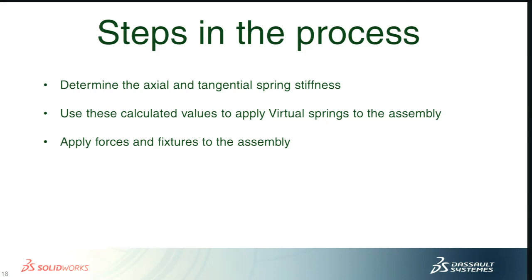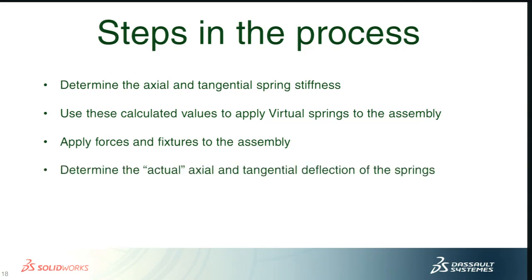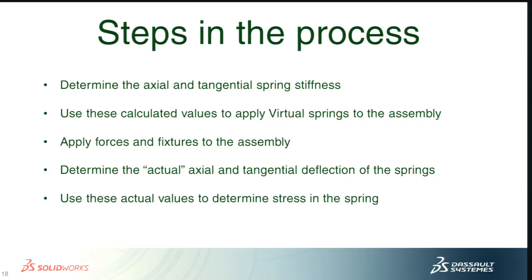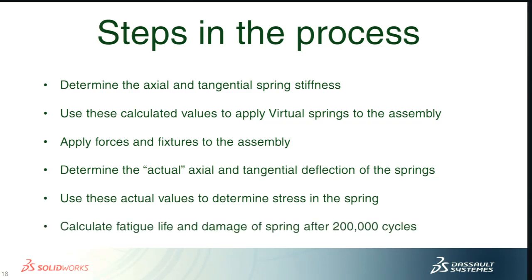We'll apply those forces and fixtures to the assembly itself. And the forces are going to be what the actual shock mount's going to be taking on in service. And then we'll determine the actual axial and tangential deflection from the assembly model. And then we'll bring those back to the spring themselves to determine that maximum stress. And then from there, determine the fatigue life if we're interested in, say, it has to go at least 200,000 cycles. Okay?